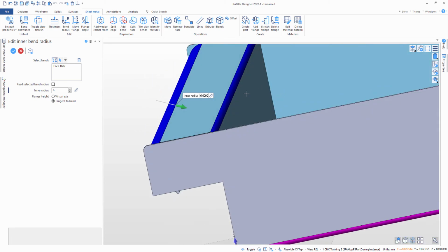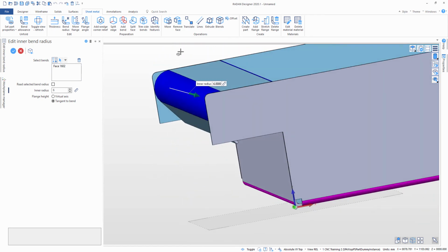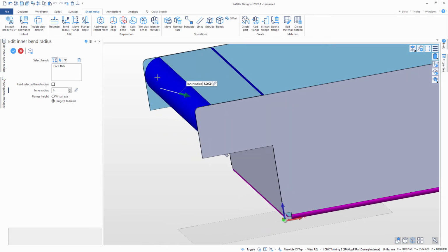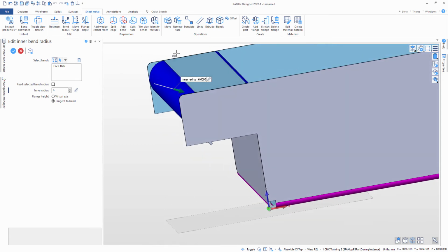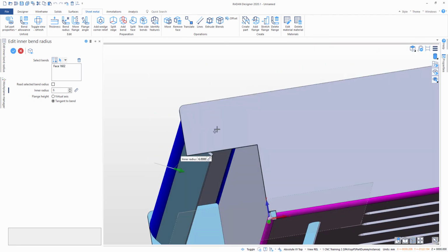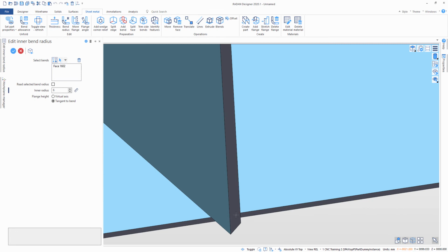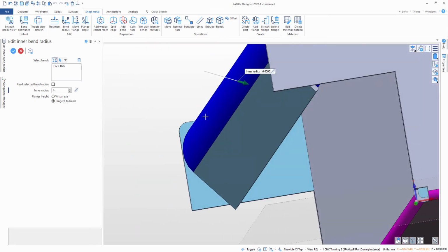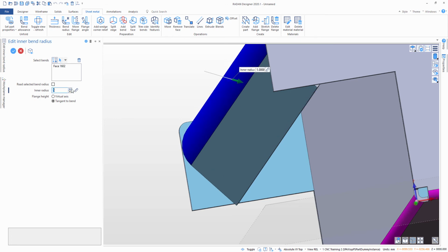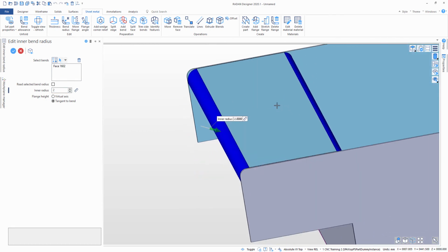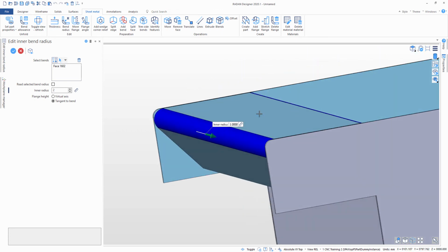That means the distance between this face and a plane parallel to that flange and tangent to this bend stayed constant, the same, measuring from the bottom to say this face to a parallel plane here. It remains constant. All flange moves, but you can be sure that after editing bend radius, the real width of your model for sharp angles stays the same.